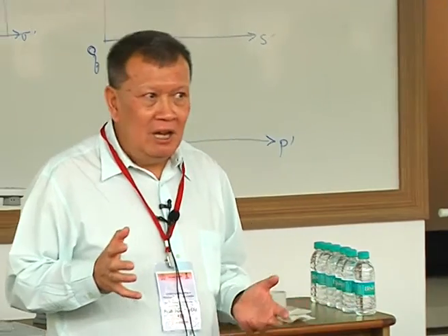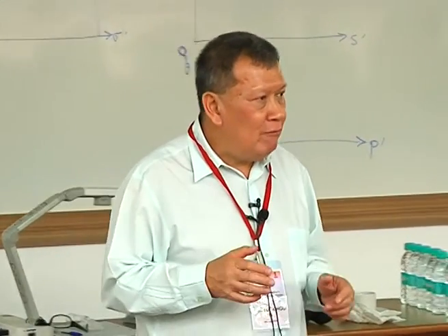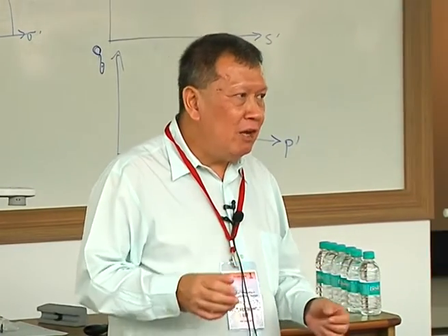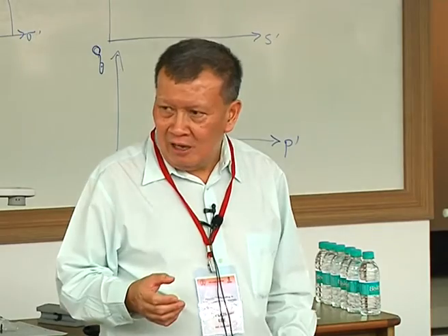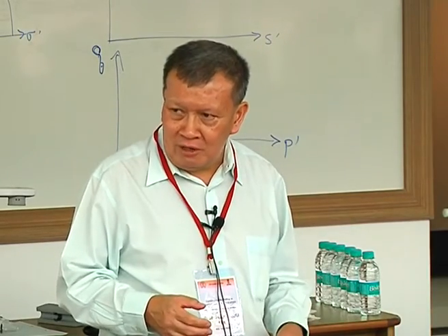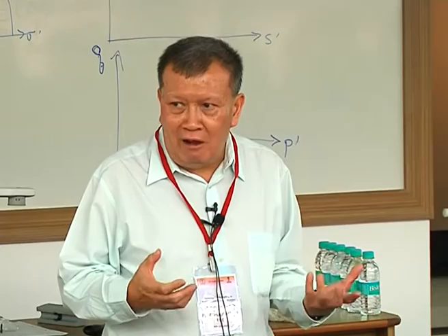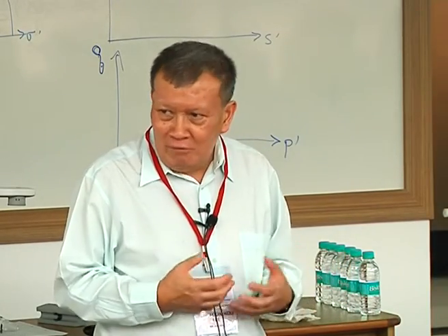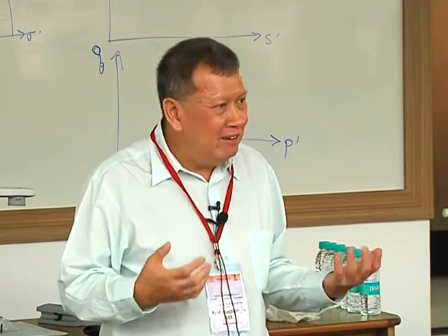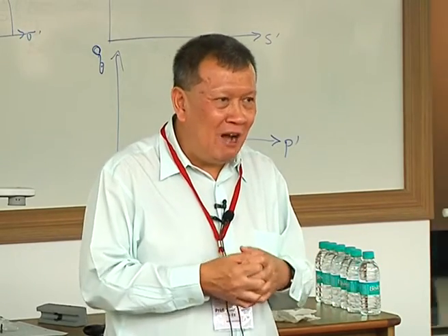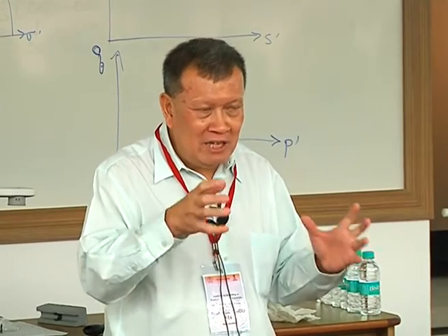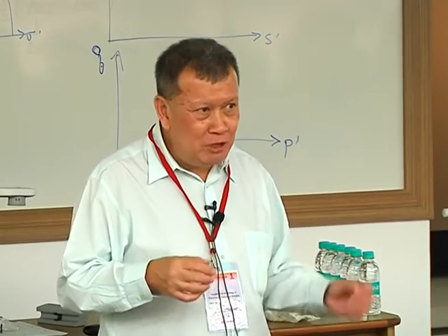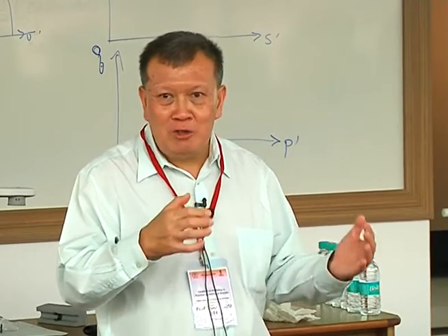To me, this is something that very few people have ever done in practice. For some reason, engineers don't say, hey, why don't I do a triaxial test and see what the thing looks like? Is it giving me a sensible result or a non-sensible result? To me, if you can't even get a sensible result out of a triaxial test, why bother with a deep excavation? Why bother with a tunnel? You know what I mean? You cannot win already. So the first thing is to make sure that for the result coming out of the triaxial test, you know how to set the parameters in such a way that you're getting sensible results. And when you change the parameter, the result changes also in a sensible way.